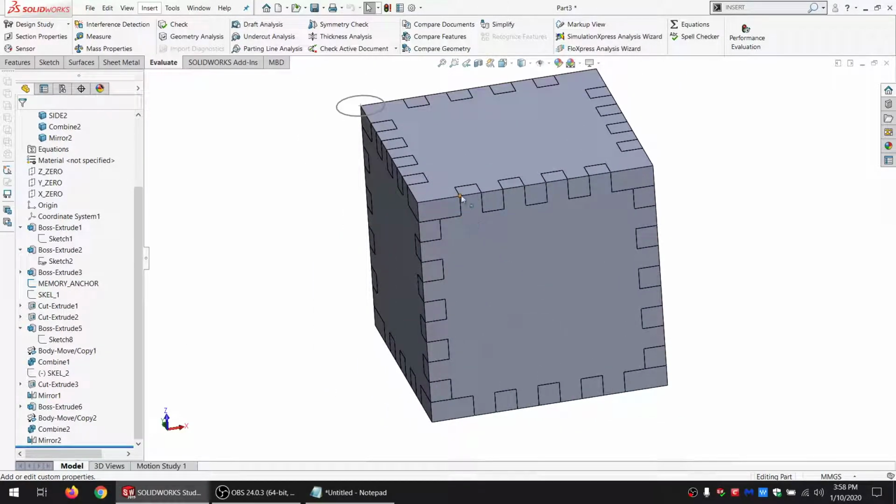The second thing is that this value here, the kerf. When we're cutting, we're going to be cutting material away. So if we cut line on line, it's going to be a little bit too small. Each of these teeth or fingers are going to be a little bit too small, which means it won't fit very well. It'll fit very easily, but it'll be kind of sloppy. Maybe you like that just because the box is easier to assemble that way. You're going to glue it anyway, whatever. But maybe it's a more complex design. You don't even want to use glue. You want it to be all press fit. That's where the kerf really comes in handy. So we're going to adjust the kerf.